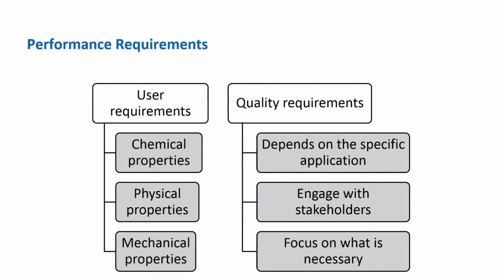When identifying critical performance requirements, focus your efforts on those that are necessary to achieve the specific function you're replacing. For instance, the level of corrosion resistance that can be achieved by an alternative to hexavalent chromium in electroplating applications. While this is clearly the primary function of the substance of concern, hexavalent chromium, other functional attributes that it provides, such as wear resistance or hardness, may have more flexible parameters to be met.